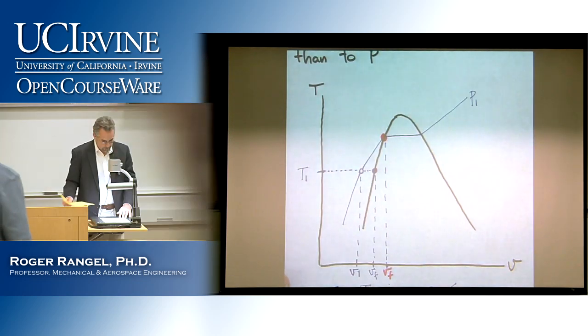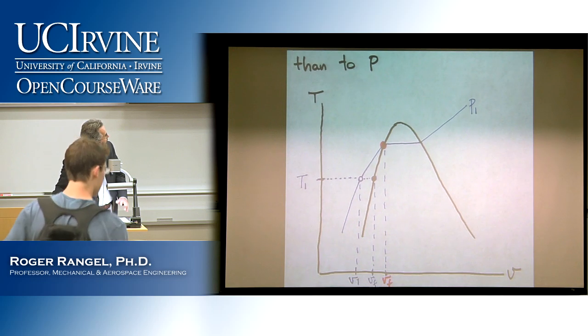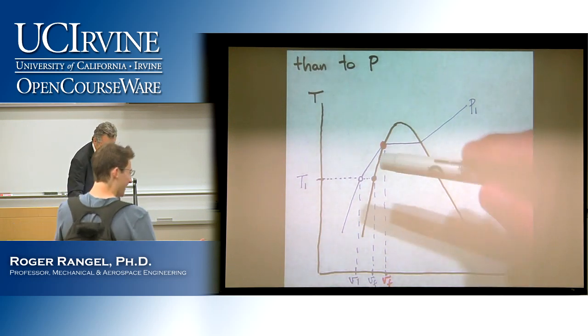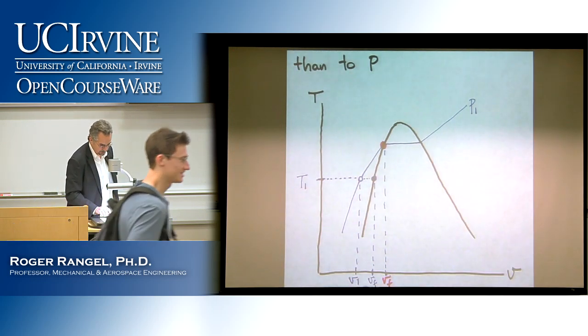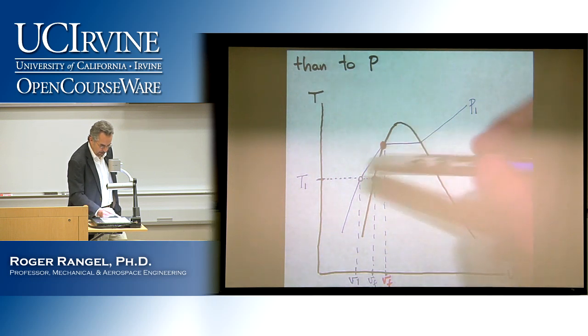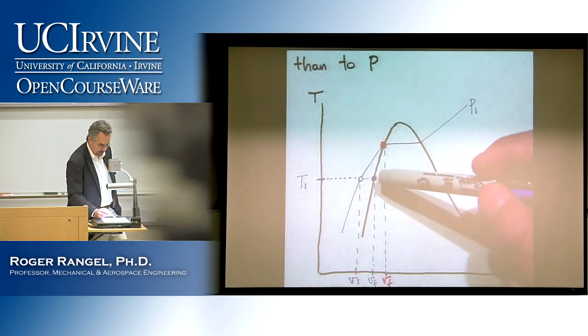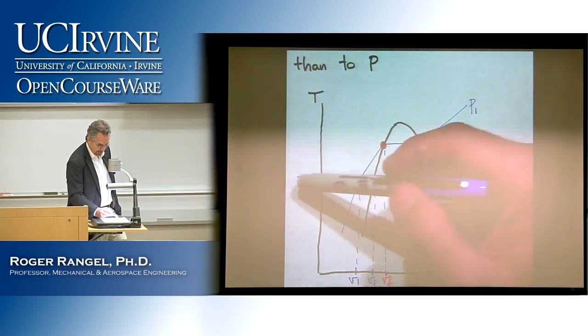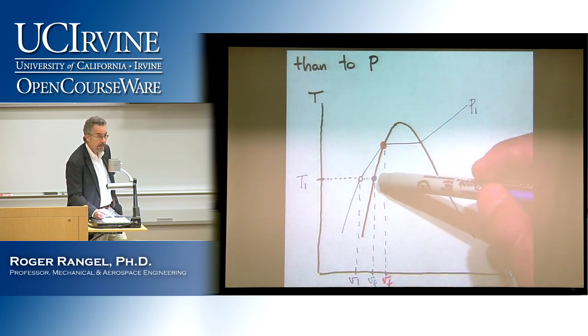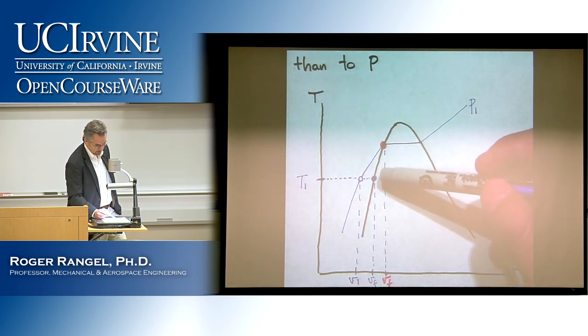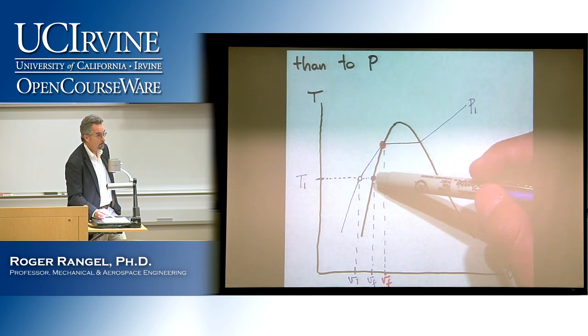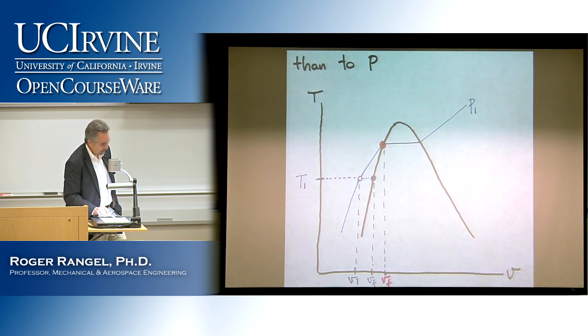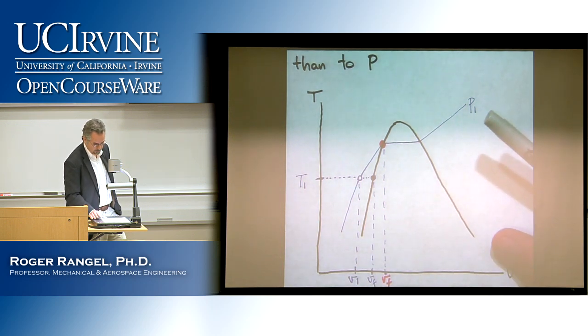So here is the, blow it up a little bit. So here's my real point, here's my real volume V sub 1, but if I ignore the pressure and just take the value of the saturated liquid at the same temperature, then I would be reading on the table a value that is corresponding to this blue, this filled circle. So that would be the volume that I denoted here at the bottom as V sub F in blue.